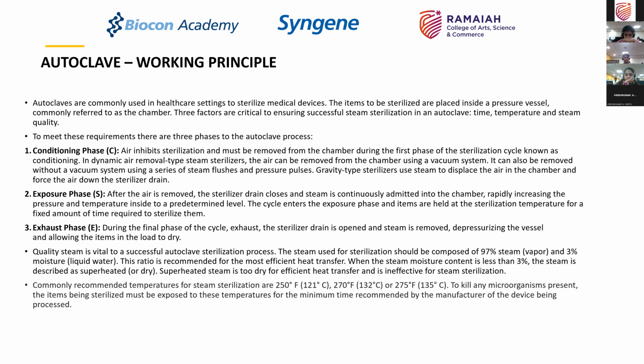And then you have to get rid of that steam, so you allow the sterilizer to drain by opening the steam exhaust. You also allow the items to dry. Now in the autoclaves available today, you do this by drawing a vacuum from the system to remove the steam, and simultaneously introducing sterile air so that you can dry the loads much faster. If you allow them to dry naturally, it will take a lot of time.